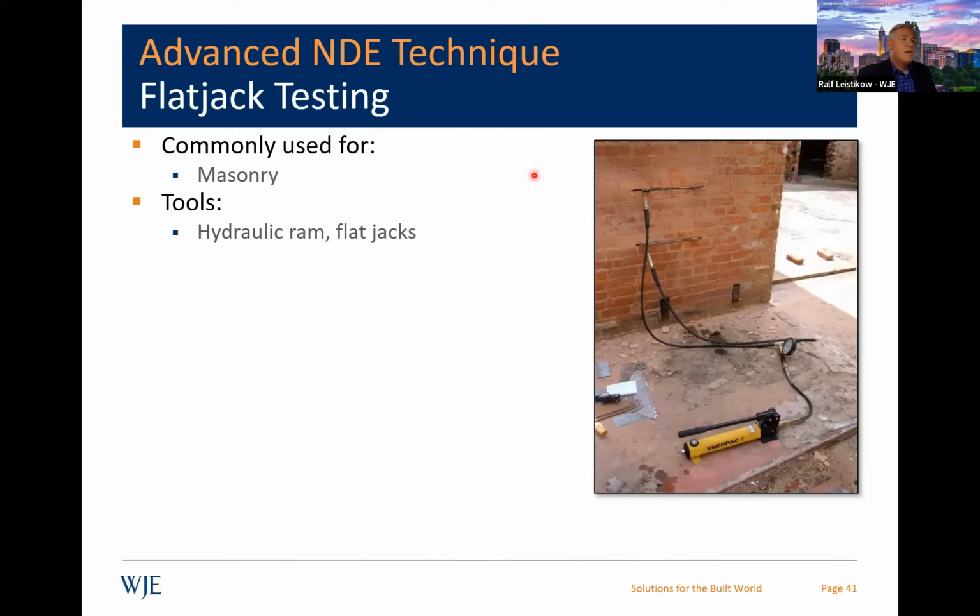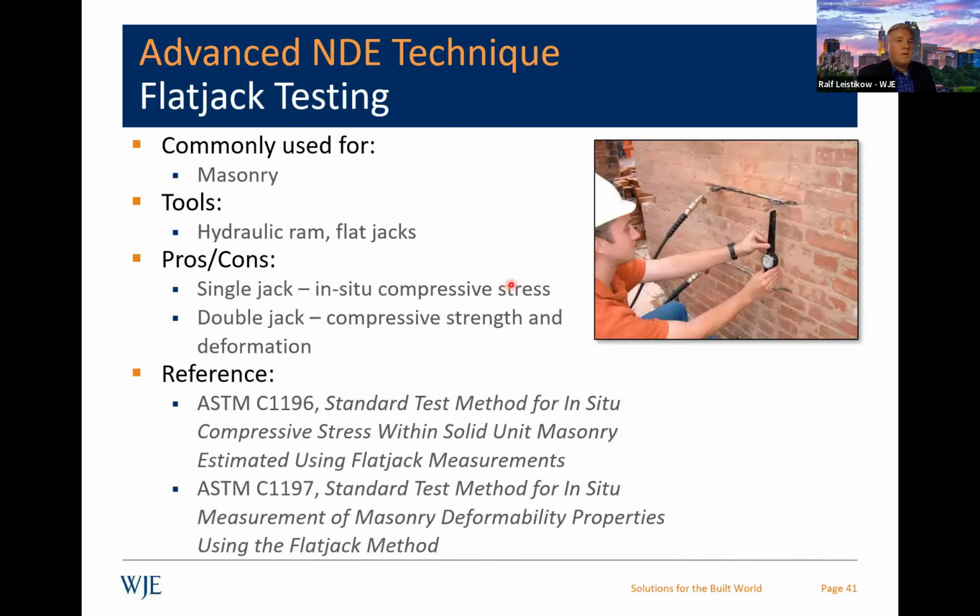But another one is flat jack testing. This is more masonry. It's like a hydraulic ram again with these flat jacks, which are basically plates that are inflated or filled with hydraulic fluid. There are single jacks and double jacks, and you can figure out the in situ compressive strength or what forces may be in the wall.